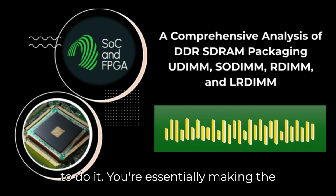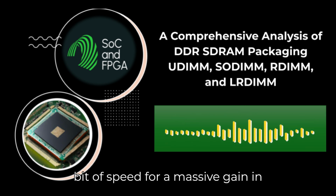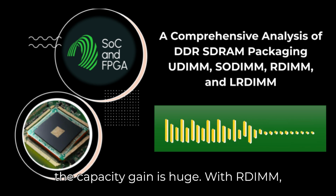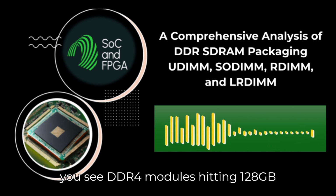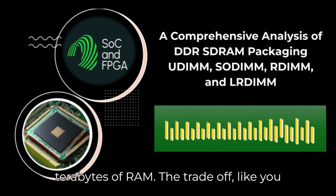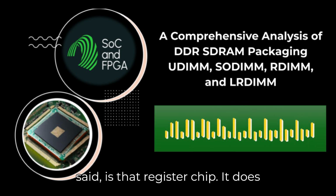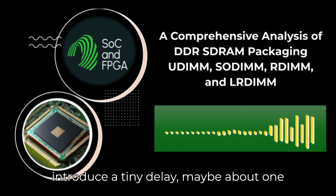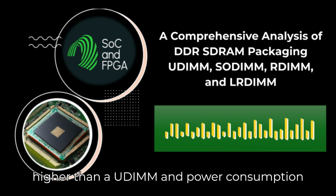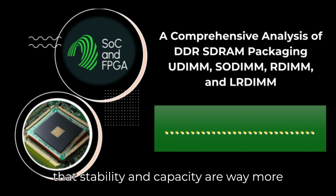That's a really smart way to do it. You're essentially making the connection less direct, trading a tiny bit of speed for a massive gain in stability and capacity. You got it. And the capacity gain is huge. With RDIMMs, you see DDR4 modules hitting 128 GB each, letting you build systems with terabytes of RAM. The trade-off, like you said, is that register chip. It does introduce a tiny delay, maybe about 1 CPU clock cycle, so latency is slightly higher than a UDIMM, and power consumption is marginally up too. But for servers, that stability and capacity are way more important.